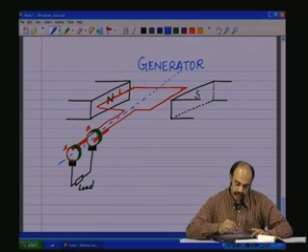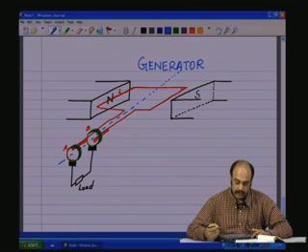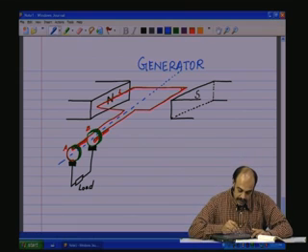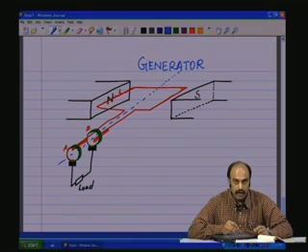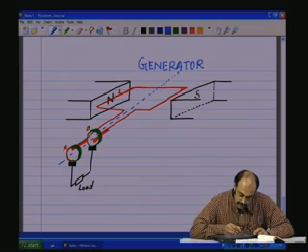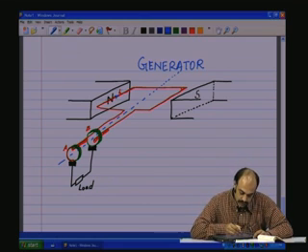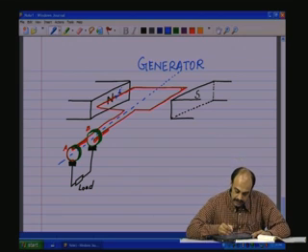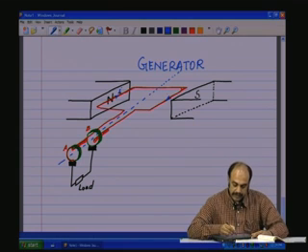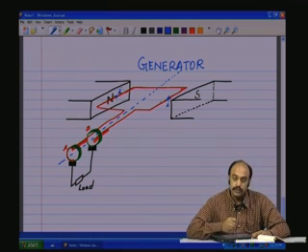So, the whole coil is rotating along the axis, the blue line as shown here. Now, this conductor here, when it is at the north pole, is going to have a positive max field, as we saw before, and let us say a current I is going to be induced in this direction. This conductor is closest to the south pole, and is going to have a negative max field, and a negative current of the other direction, same amplitude, is going to be induced in it.